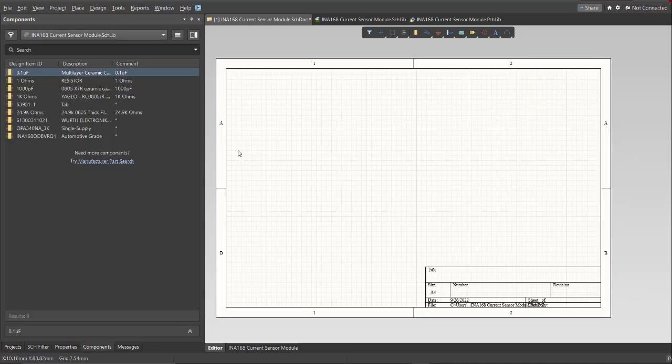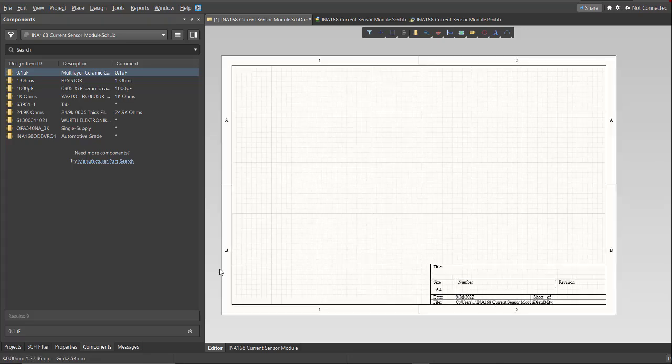After you finish all the components in the library loader, next we're going to input all the libraries in the schematic sheet. To be able to do that, just click on Components on the panel, then just drag the components into your schematic sheet.